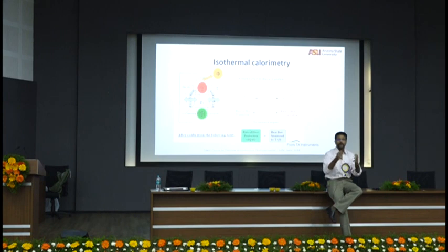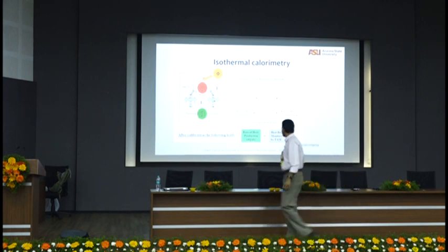So you have a problem with a concrete. Somebody tells you to investigate what it is. You take a sample from one place and make a conclusion. You're more often going to be wrong than right, because you're seeing only part of the story in one part of the structure. Heat of hydration directly influences how much heat is exchanged and how much heat is used to equilibrate the process, resulting in different microstructures in different locations.